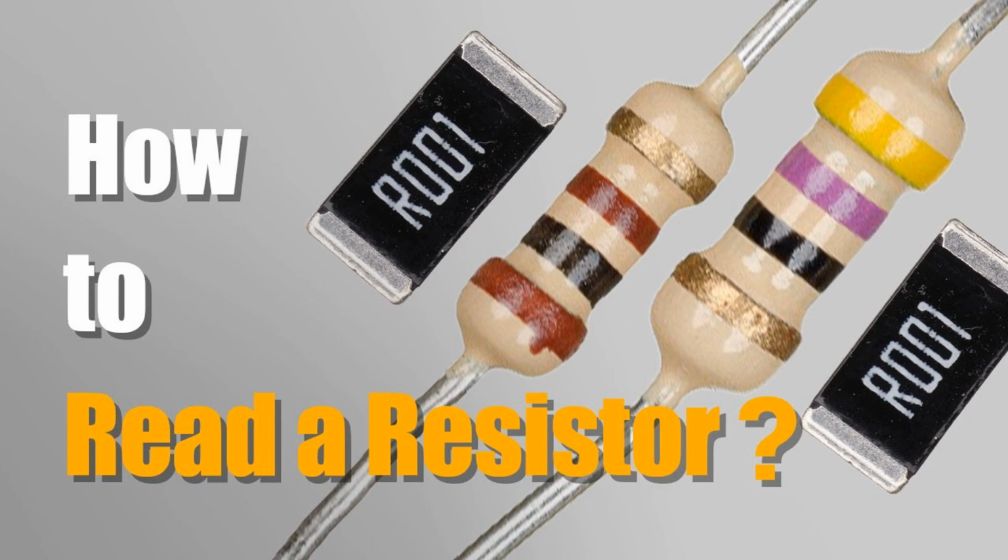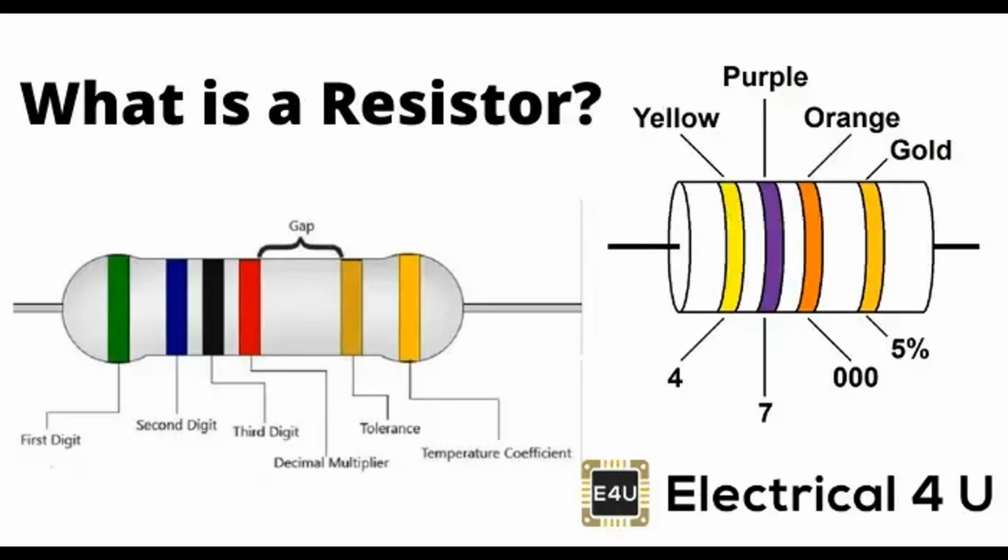Example circuits. Pull-up resistor example. Suppose you have a push button connected to a microcontroller input pin. A 10 kΩ pull-up resistor is connected between the input pin and the 5V supply, VCC. When the button is not pressed, the input reads 5V, logic 1. When the button is pressed, the input is connected to ground, and the input reads 0V, logic 0.